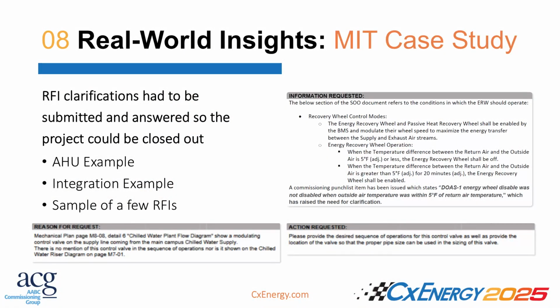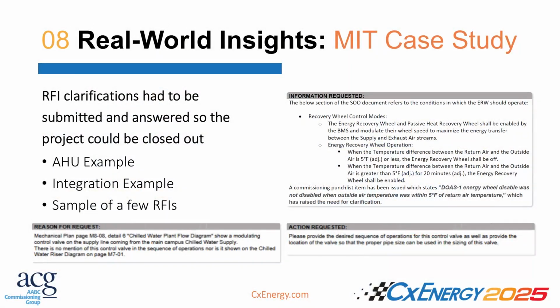Yeah, again, so based on the pre-verification test, I just put in a couple samples of some RFIs that came out from it. Some of those endless loops, pumps not working, desired sequence for control valves because it wasn't shown, a modulating valve that nobody knew what it did, but it was installed in our system. Things like that, we find that quite a bit.